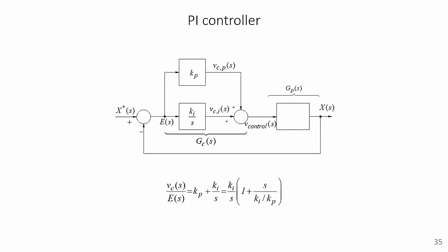There are other algorithms which have various advantages and disadvantages, but for this session we will simply stick to PI controllers. Traditionally, there would be a D component involved, becoming a PID controller, but we will avoid a D controller because, as we will see, all of our measured signals have a significant amount of noise. And wherever there is noise, we avoid a differential controller. The differential controller is going to amplify the noise, which is going to completely mess up the algorithm.